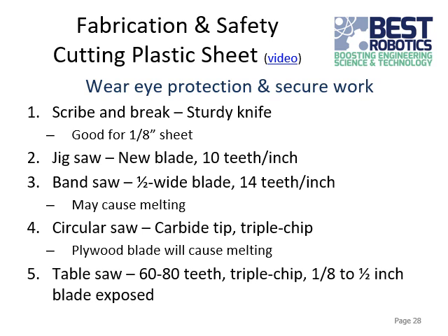You can use a bandsaw or a circular saw or a table saw, and similar things apply for all of these. I won't go into too much of the details here, but it's here for reference. Just know that with some blades, and when it's going really fast, it can actually melt the plastic as it cuts. It's not necessarily a bad thing. Just be aware of that.